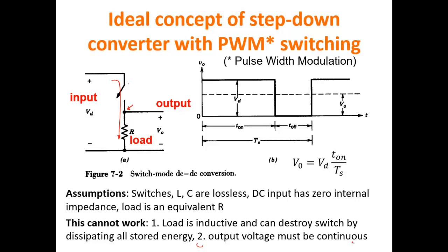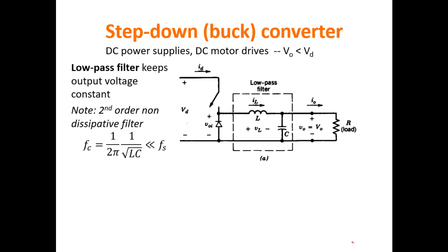And luckily, it is a relatively easy thing to do, because we just need to change the converter in this way. You see, the principle is more or less the same. This is the input voltage that is not regulated. This is the load, and this is the switch.